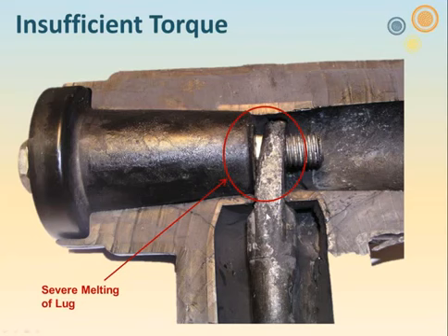Now, when you first look at this picture, I'm sure the first thing everybody keyed on was the fact that we are looking at 1/3 of this lug, and we don't see any crimps, which means the first crimp is way down. Even if they started down here and all the crimps were put on right next to each other, there's no way that they would be able to get the proper number on.